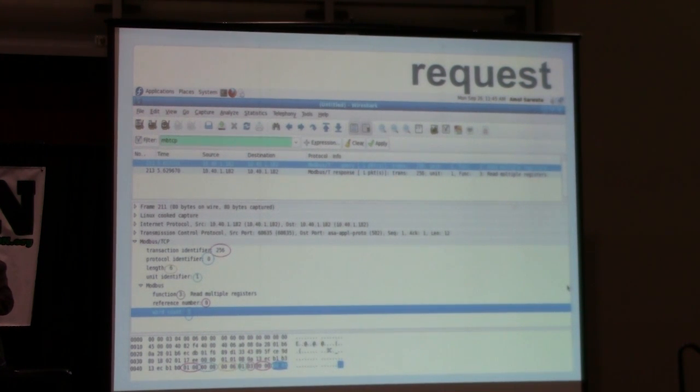we didn't have to modify or write plugins for any of the packet sniffers. So what usually happens is if you are debugging a new protocol or an unknown protocol, the packet sniffers cannot sniff the packets because they don't know about that protocol. But most of the packet sniffers, actually I would say all of them, Wireshark or any of them, already have built-in support for Modbus and a lot of SCADA protocols. So if you do this in your environment, you wouldn't have to do anything special. You just sniff the traffic, and it will show you clearly what's being sent.